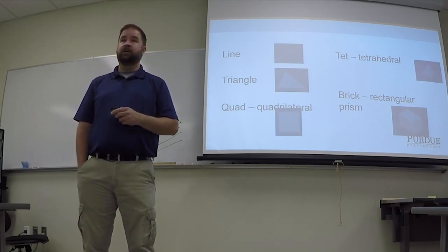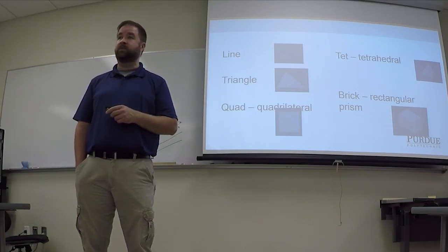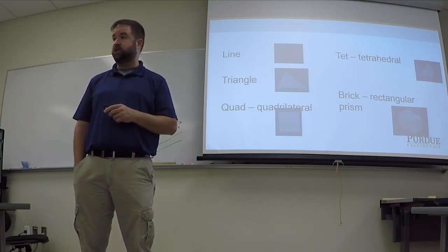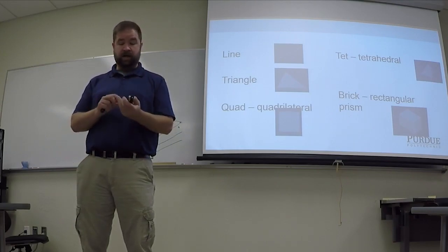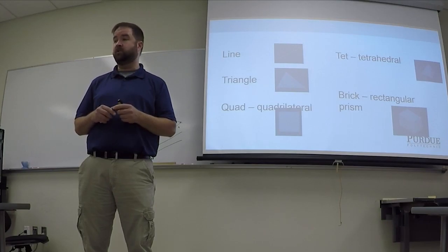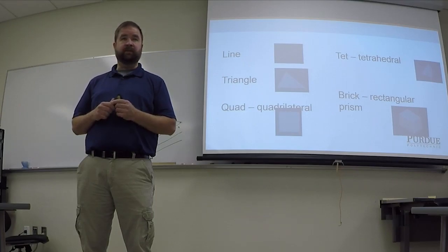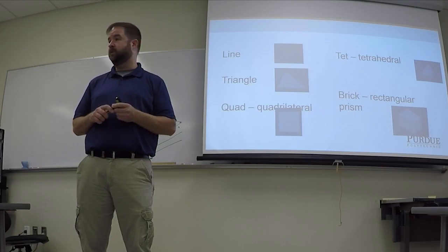Yeah. Okay, so when we mesh something, if we're using 2D or 3D elements, we should see triangles being meshed because that's what SolidWorks uses. Some other software uses rectangular elements. ANSYS, for example, you can choose to use rectangular elements. I think there's some options. I'll have to go back through and dig through the SolidWorks options.